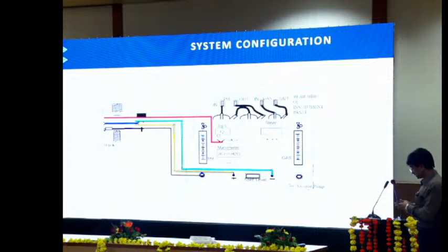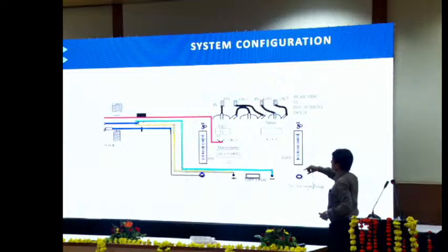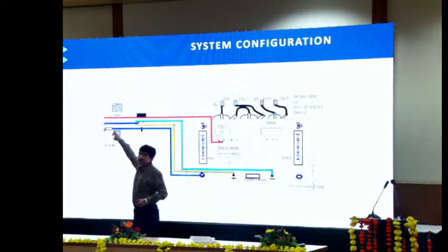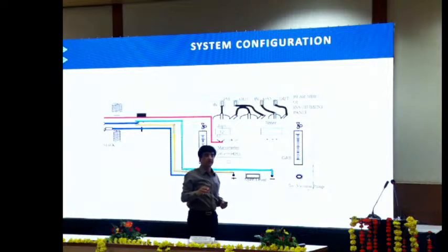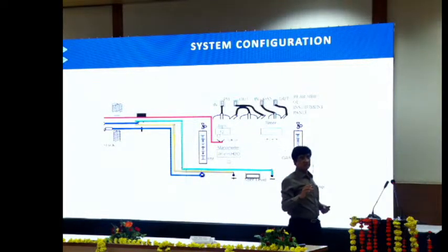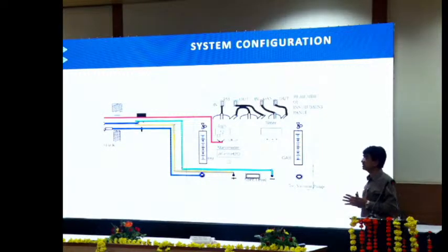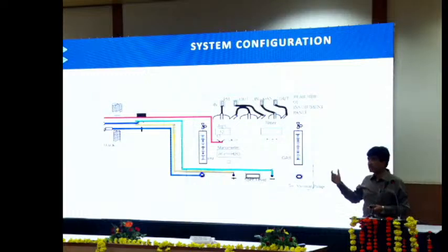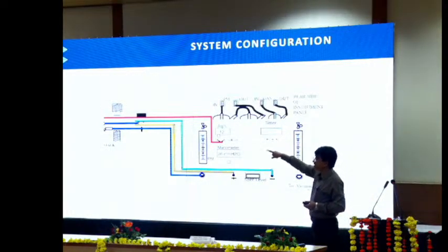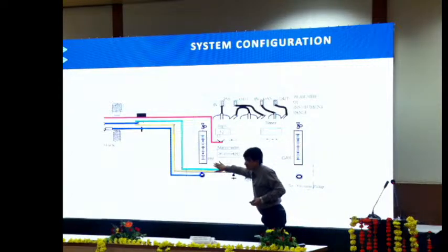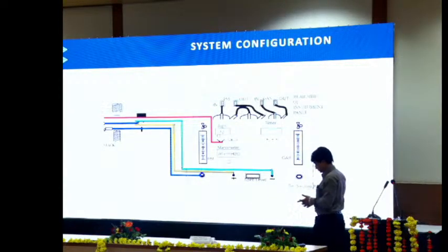But in order to show you pictorially how things are being done, the third part comes, this nozzle. See, this nozzle and there is a filter holder. This filter holder contains a thimble. The thimble is a filter only, which is going to collect all the dust particles which are going in the stack. So we need to collect those dust particles in that thimble. It is connected to 2 rotameters, one for the particulate and one for the gases.